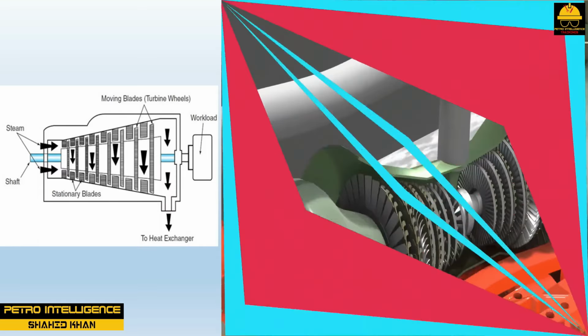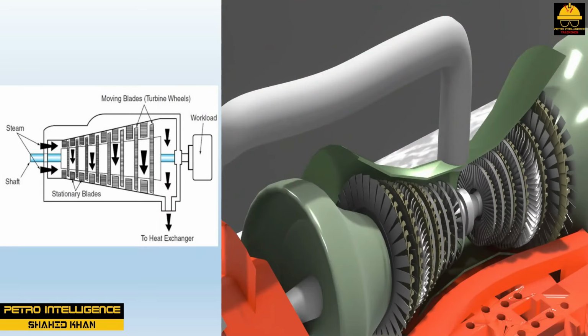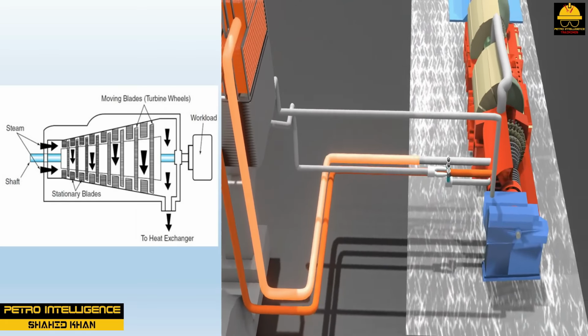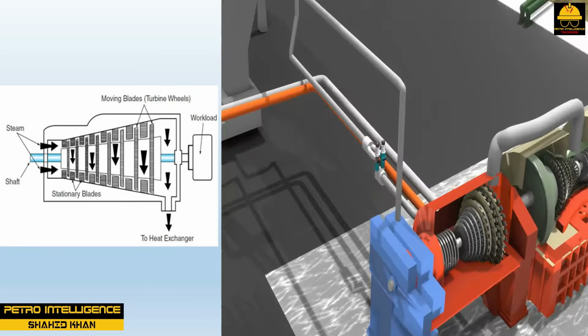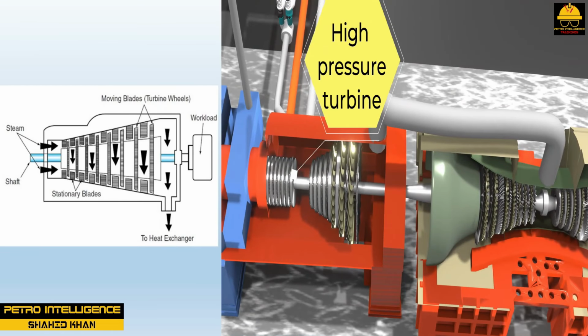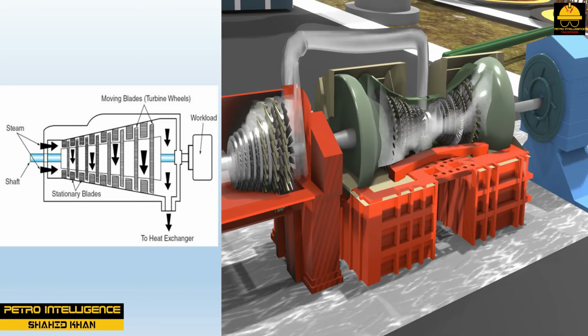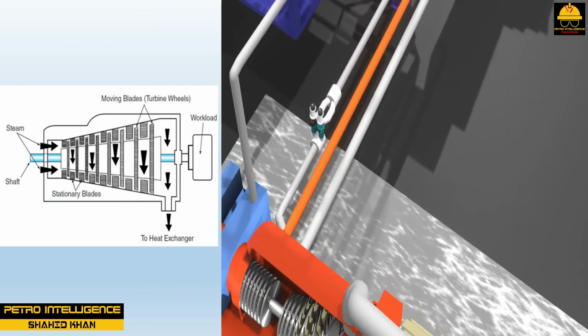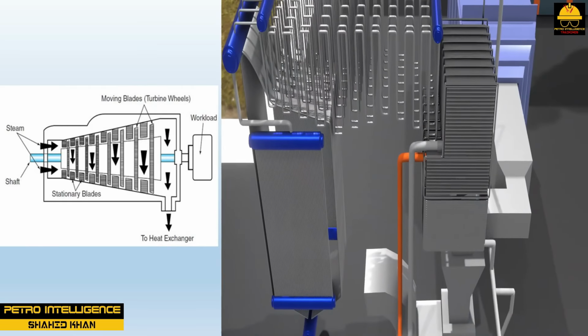The steam used to operate a steam turbine is produced in a boiler. Boilers produce steam that can enter a turbine at temperatures as high as 538 degrees Celsius, or an average of 1000 to 1050 degrees Fahrenheit, and pressures as high as 3500 psi inlet and 200 psi outlet. Steam turbines can also run under a vacuum. High-pressure steam is admitted slowly into a turbine to warm it up and remove condensate, that is moisture produced by condensation. Steam turbines are used to drive the electric generators in modern power plants.